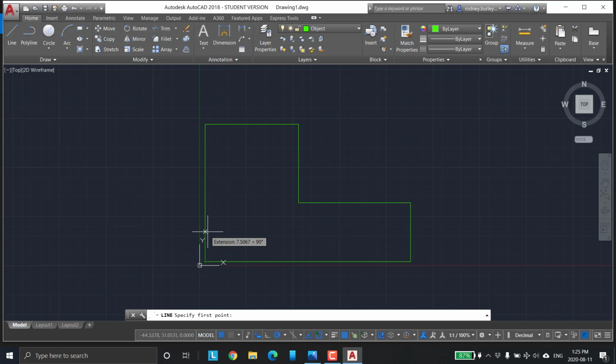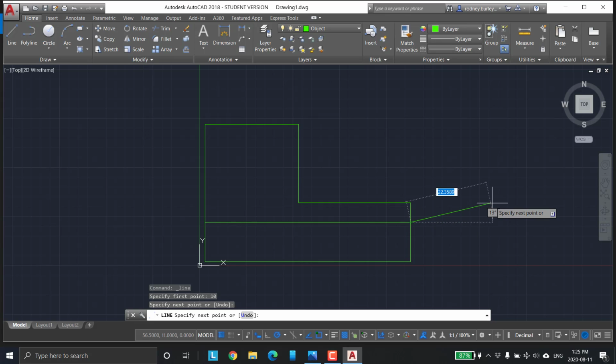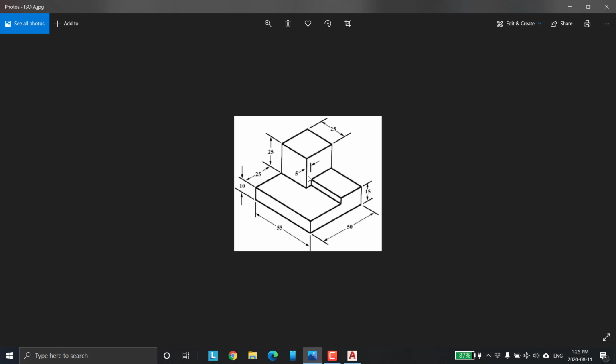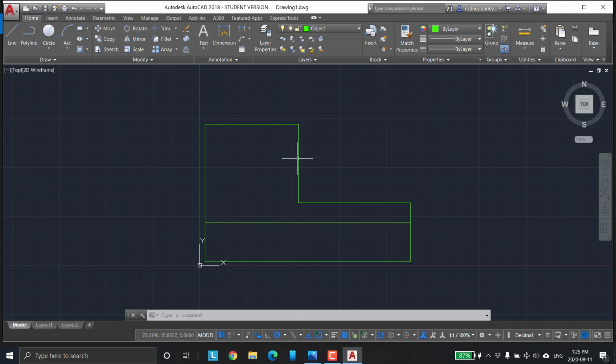And as you walk up, as long as you stay on the line, you type in 10, enter, and it's locked in now at 10 millimeters up. Comes straight across like so until it locks onto that, and hit the escape key, and that's done. So now if you look, there's one little line missing, that guy right there. Not this one because he's hidden behind that, but this one should have gone right the way down.